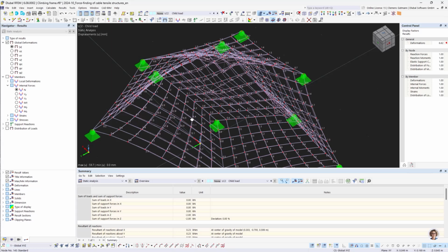Still, I think okay, but of course, there's an influence of the pre-stress level later on, not for the form finding, but if you use the form found and pre-stressed structure for additional loads, it makes a difference what pre-stress level you have applied to the model.